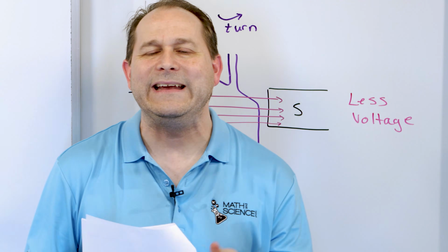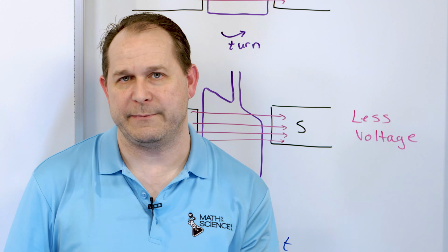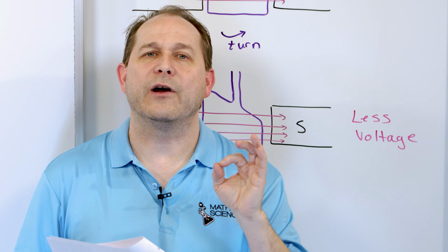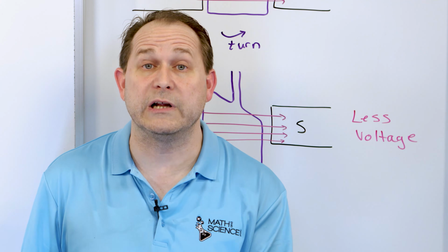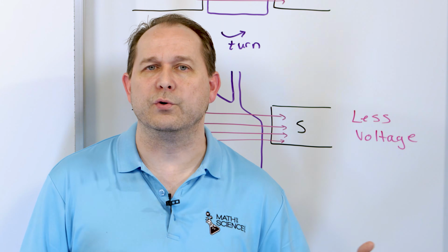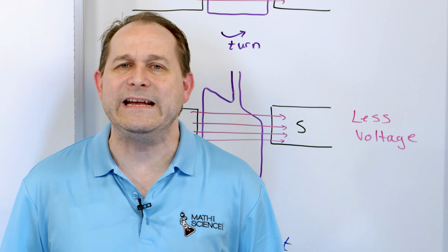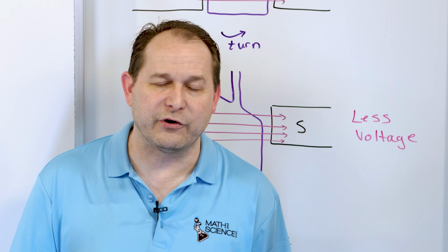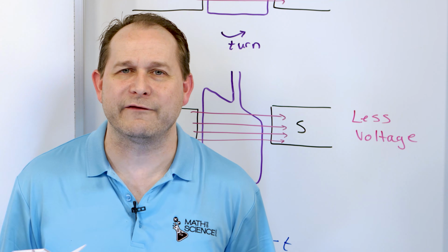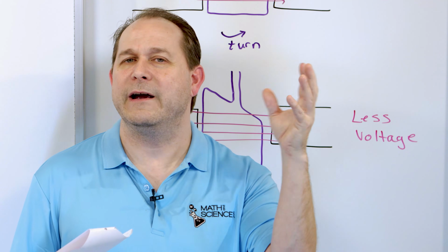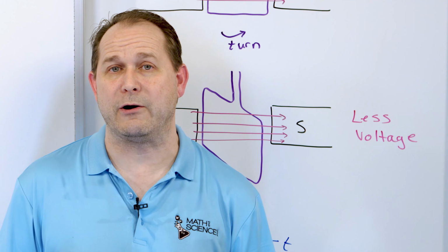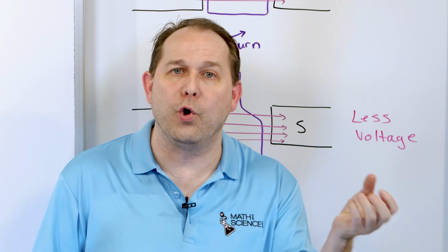So the reason why AC current is so common, other than the fact that it's more efficient to transport, is because all of these generators, even nuclear power plants, the way a nuclear power plant works, yes, there's a nuclear fuel making some heat, but all it does is heat up some water, which turns into steam, and the steam turns a generator. So we're still turning generators, which are coils of wire in a magnetic field to generate all of our electricity, even if it's a nuclear power plant or a gas power plant or a coal power plant.